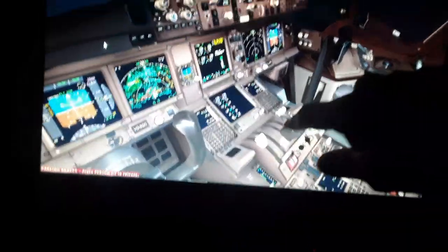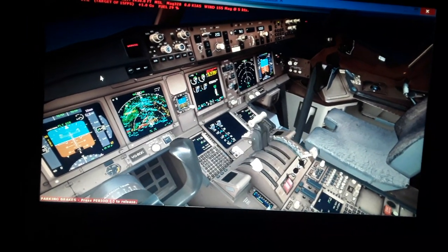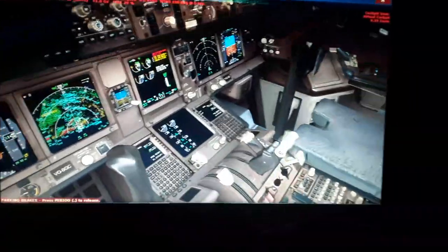Then I'm going to show you the thrust levers, and how you can use the thrust lever position in conjunction with the auto throttle system. Either one, you can disconnect the auto throttle while trying to fly manually with the thrust levers. They command the thrust and adjust the airspeed this way, and the altitude of the aircraft in flight. You will see the thrust levers, how we can advance them forward or aft, what they can do, and other things that interact with the thrust levers.